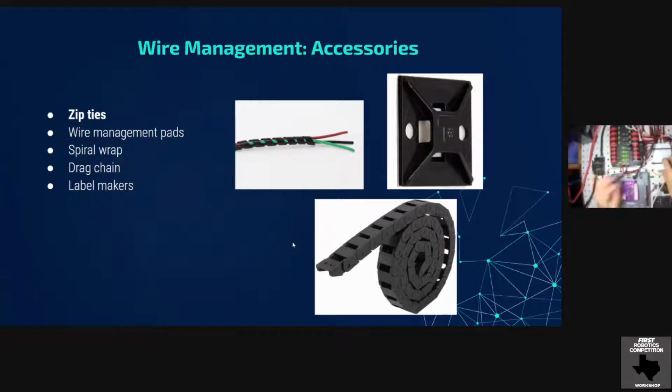So I'm going to drill this into your minds. Do not physically attach your radio in any way other than zip ties or Velcro, because your radio needs to be flashed, which is basically rewriting the radio's configuration for a competition versus a shop setting. And you're going to need to put this on and off and on and off of your robot repeatedly. I promise you it comes off the robot and back onto the robot 100 times during the season.